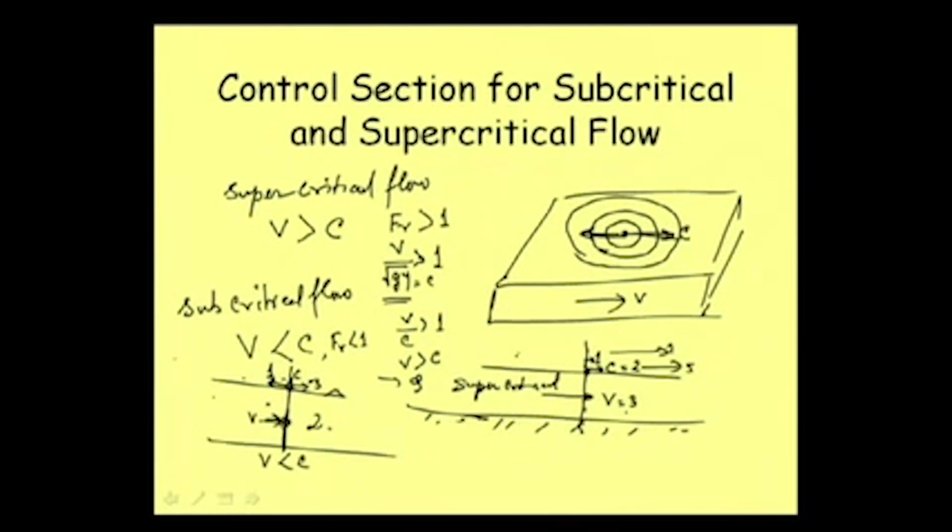This is what I have tried from my side to explain with a simple example and from physical understanding of the situation, which really shows us why the control is at downstream for subcritical flow. If you do something on downstream, this is influencing the upstream. So, if we want to compute subcritical gradually varied flow, then we should see what is there at the downstream point, that is, the control section, where we get that value, and that value is influencing the entire flow. So, we will have to start computing from the downstream side.